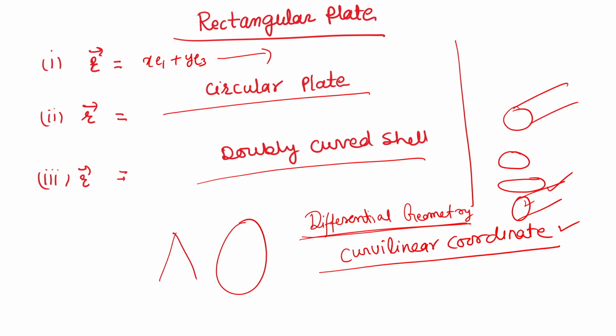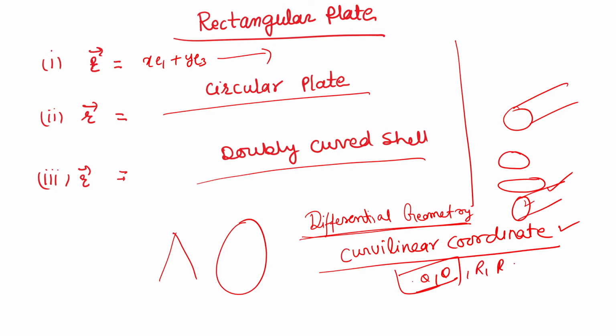So, position vectors can be developed, and these position vectors are easily available for a given curvilinear system, means coordinates will be given, alpha and theta, whatever they will be. Based on that you can develop. So, for developing shell theories, one needs to have a proper position vector system, and can take it from the book or develop it themselves, and then find out the R1 and R2, A1 and A2 for the particular shell. These 4 parameters only will be required. If we know these things, then definitely a 2-dimensional shell theory or a 3-dimensional shell theory can be developed properly.